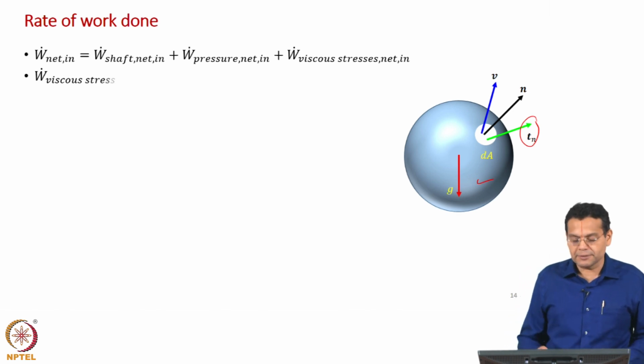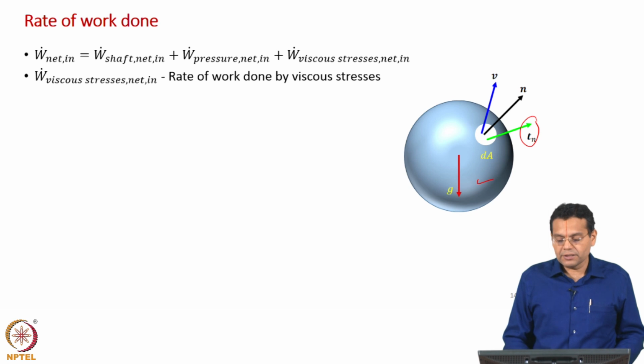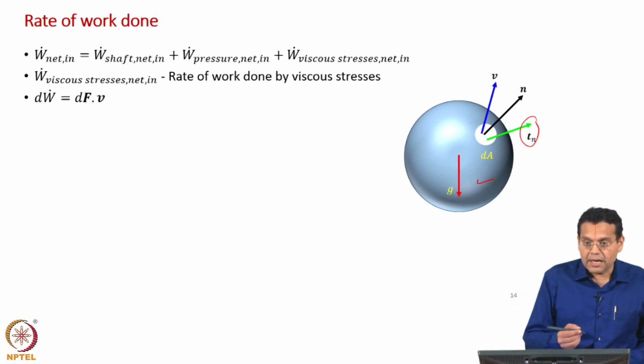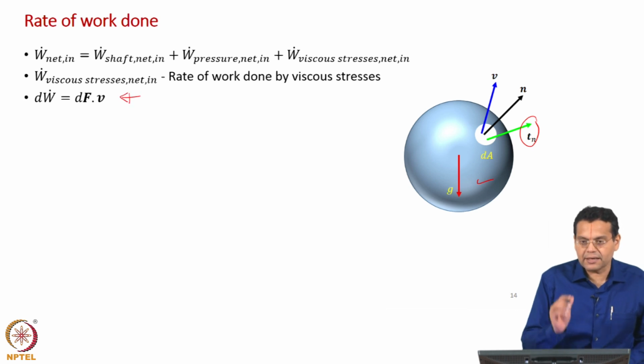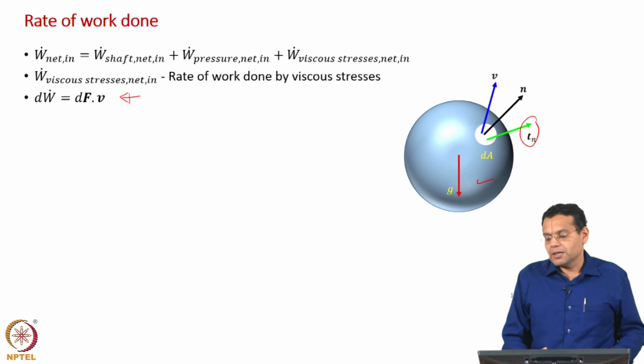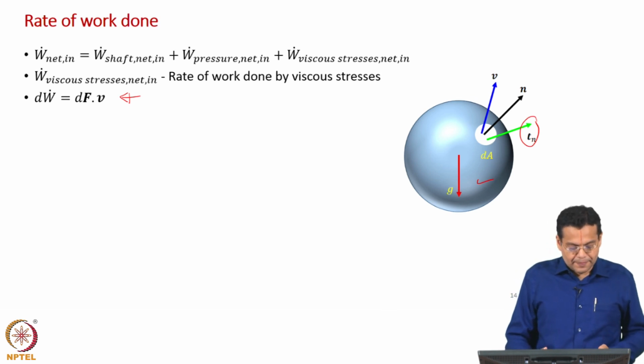Once you understand that, this becomes easier. So, the rate of work done by the viscous stresses or viscous forces, as we had discussed earlier, and as I told you earlier, this expression is very general, just relates the differential rate of work done to the differential force and the velocity. Earlier we applied that taking the force due to pressure. Now we are going to apply that taking the force due to the stress vector, or the viscous stresses.